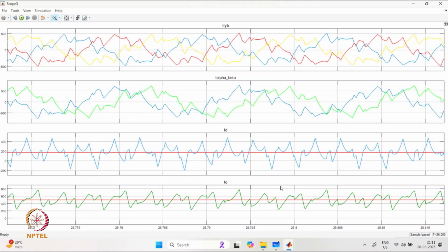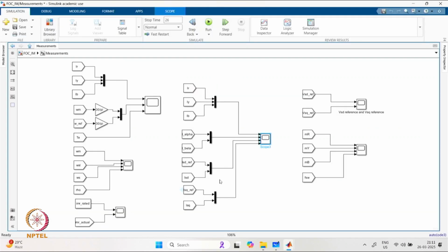So these are some of the things which we need to take care while designing the pulse width modulation technique. And many a times, because for high power motor drives, we do not have many options available for reducing the current ripple. So this is where we need to go for either special PWM techniques, or we need to go for some other topology for the power converter. However, we have seen in some of the complex structures, having more number of devices, more number of power converters in the system can only complicate the electronics design and other systems coming over there.